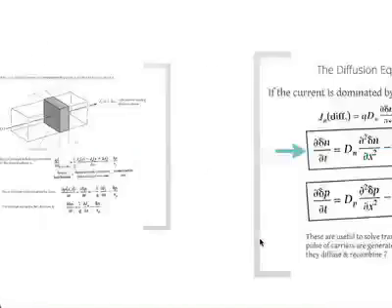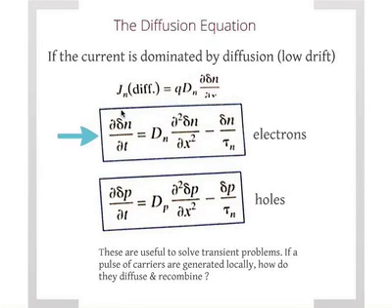That's all we did, and we get something like that, which basically says that the rate of change of concentration should be balanced by the diffusion current and the recombination. So the total rate doesn't change over time at all. Okay? This, by the way, is not necessarily steady state. This is also applicable for transient. We'll set that equal to 0 in a second, so I jumped the gun a little bit. So we haven't reached the steady state yet.